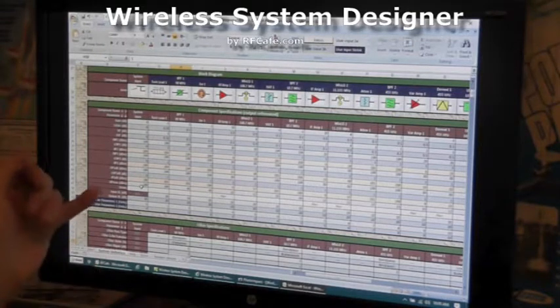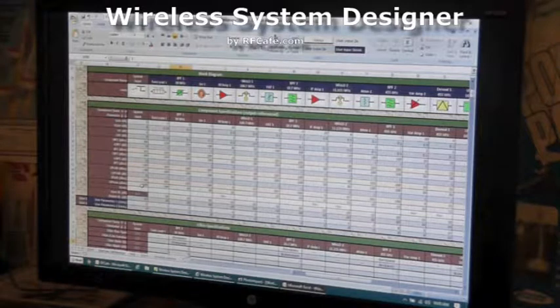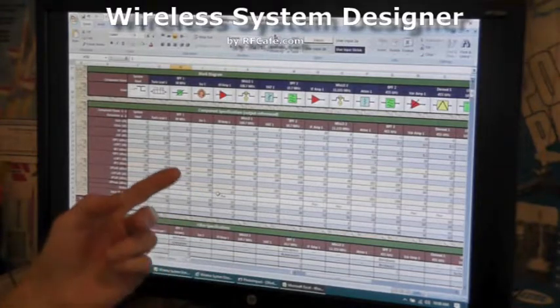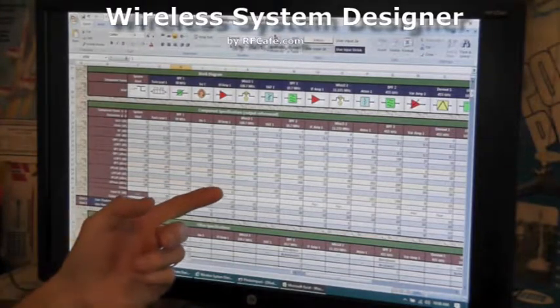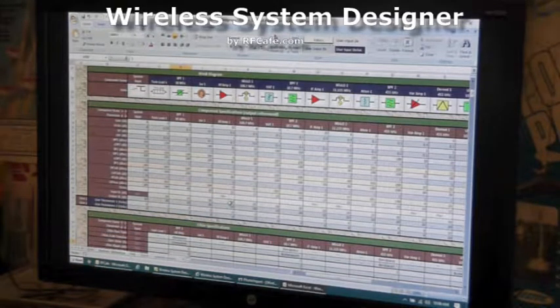I put an output max power cell in there just for you to use as a flag for yourself, so that if at any point along the cascade your gain would cause the power, assuming linear power, to exceed a certain value, you're aware of it. If it happens, you put that number here, and if it's exceeded, then I'll throw a flag up down here for you. No big deal.